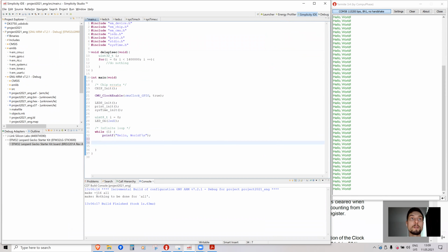And instead of calling that, we will use a very common trick. We will put the microcontroller to sleep after writing hello world, and it will just be in sleep mode. Its clock will be switched off so that it saves power, but the real-time clock is running from a separate clock source.